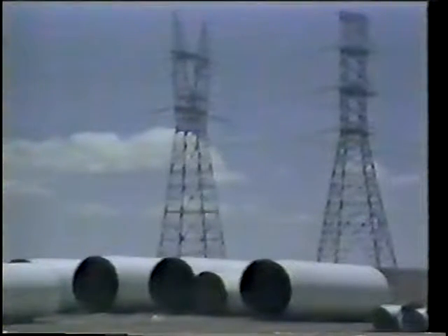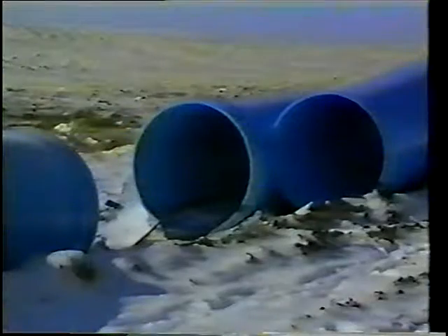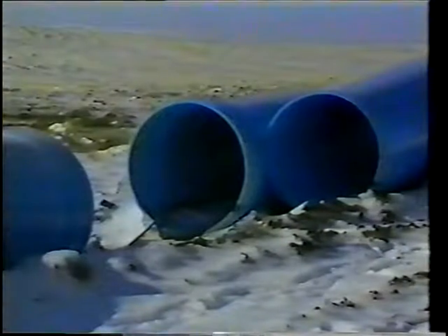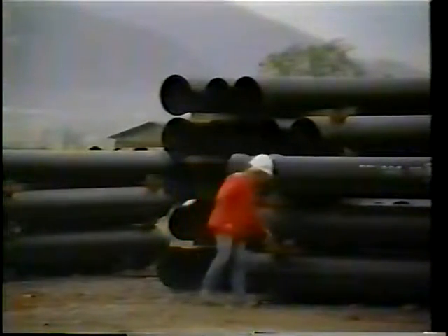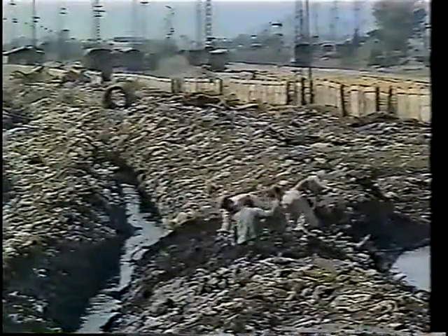Investigations may be needed to identify the presence of stray electric current or contamination from petrochemicals or solvents. The engineer must also establish whether any extraordinary live loads may affect the pipeline. These and other environmental issues will influence the choice of pipe and the design and construction of the pipe soil system.